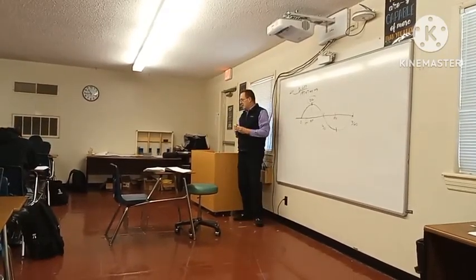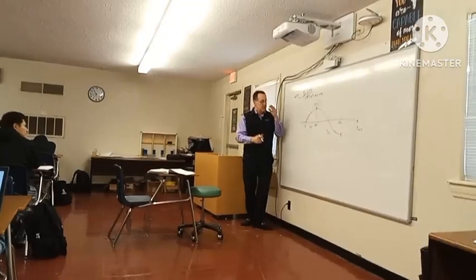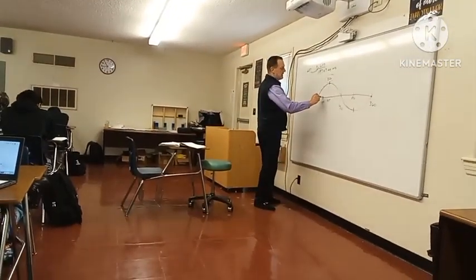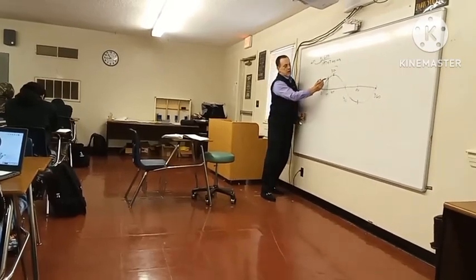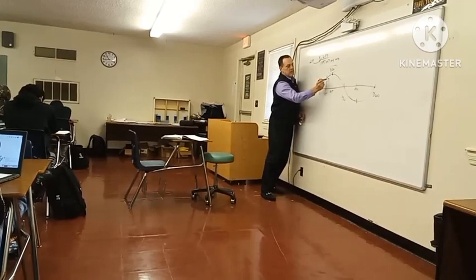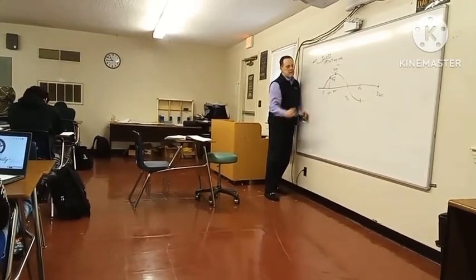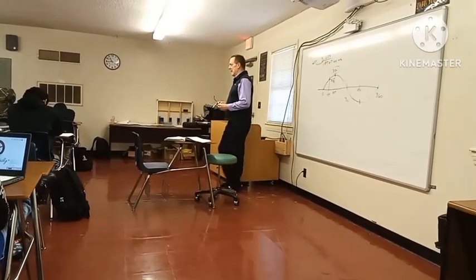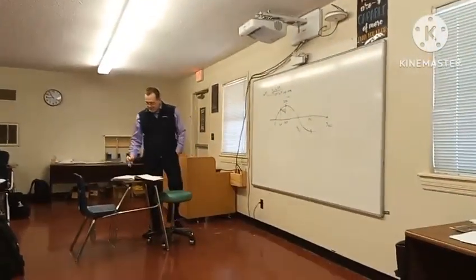Now, don't get confused and think that because we're at 45 degrees, it should be half. Because of the curve, and because it's gradually slowing down on the curve, if you went across here, that would be 70.7% of the peak value. Y'all see where that happens? So it's at the 45 degree mark.